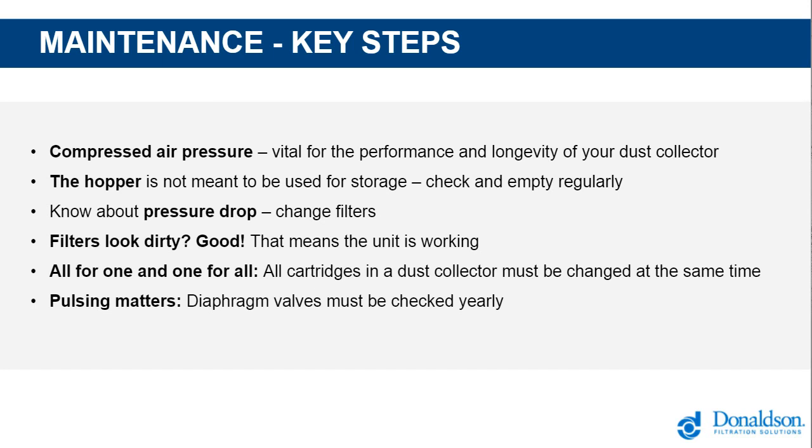It's really important that actually takes place, because if only half of them are changed, the air on the new cartridges going in would actually direct itself through its easiest route. So therefore, it will concentrate the airflow and obviously the dust and the material that's being collected onto those specific cartridges.